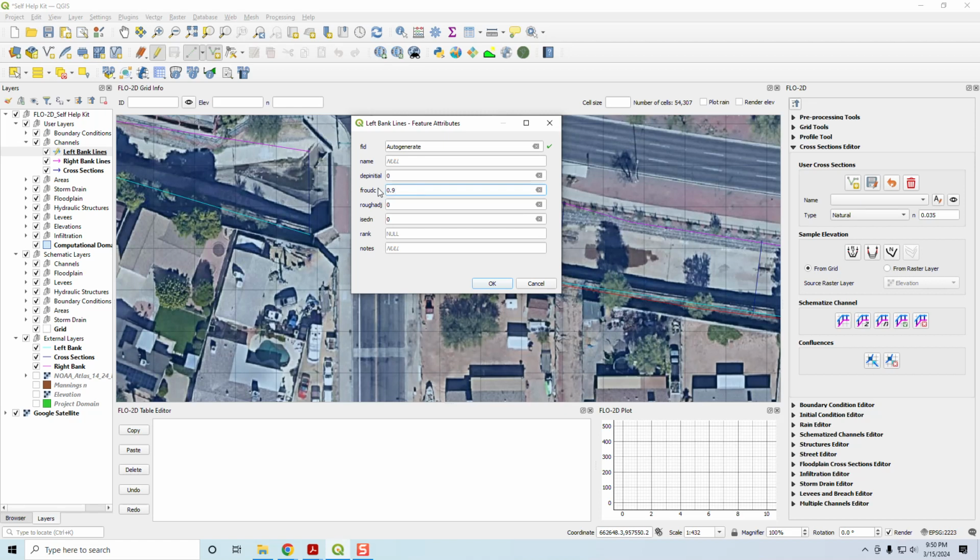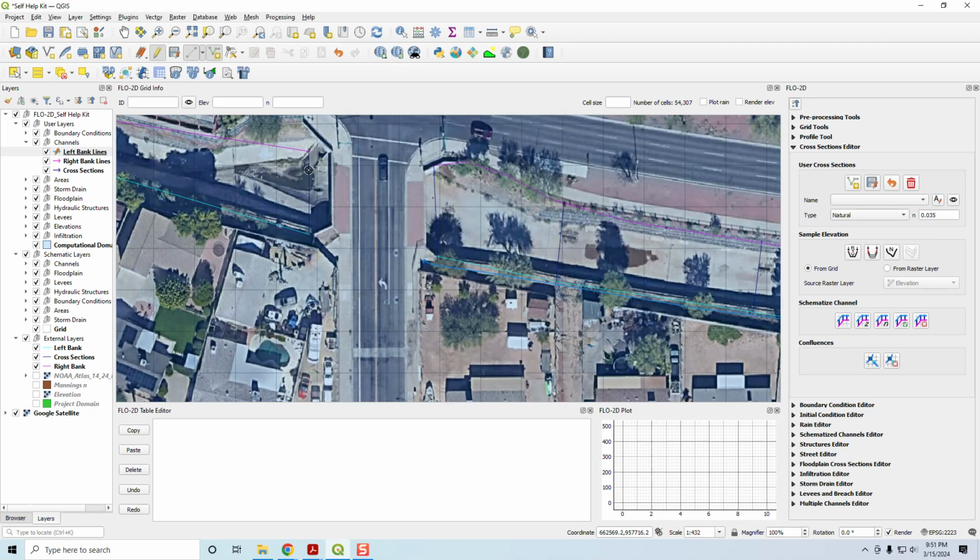It could possibly go supercritical, but I think they try to design channels that don't go supercritical because they don't want to tear up their concrete, but that doesn't mean that's always possible. But that's usually why they have drop structures. So that one's done. Let's work now, and again we're going from upstream to downstream, left bank looking downstream.